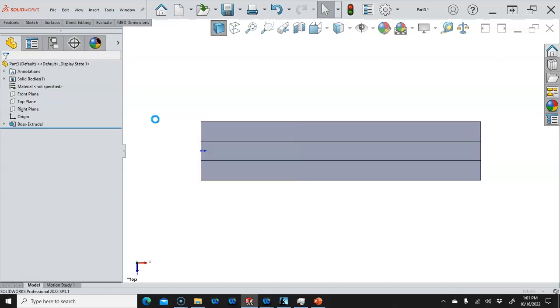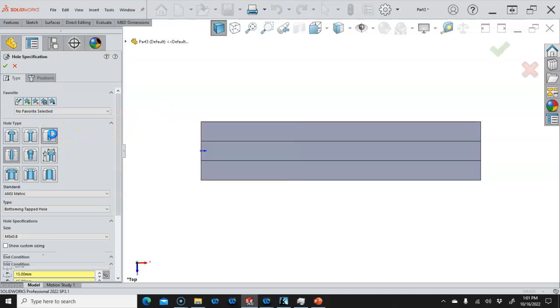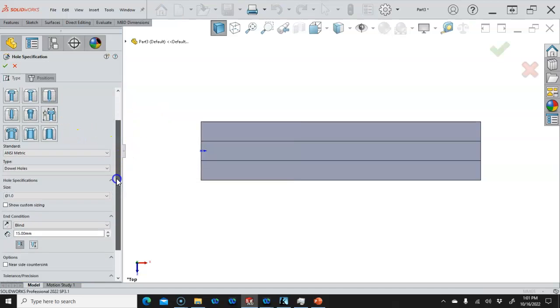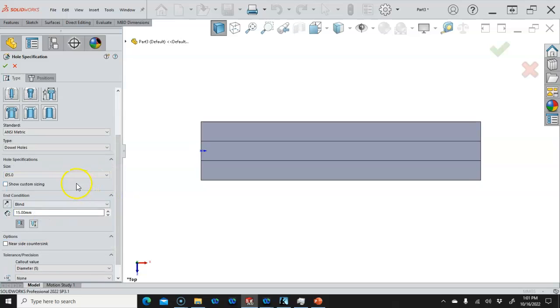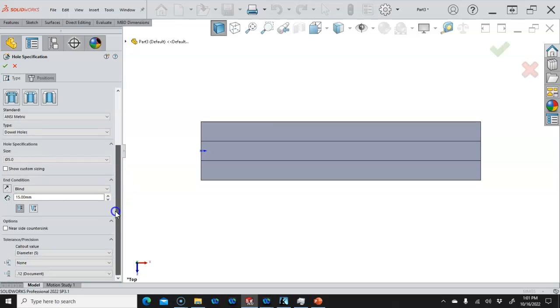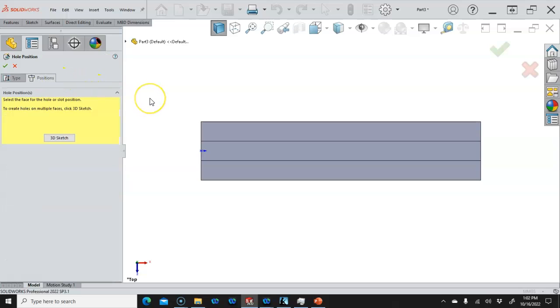And we're going to put in the 5mm dowel pins. And really for this assembly, pressing those two, there's no compressive force for the geometry to hold it in place. So if there's vibration or anything going on, then it would probably work loose.